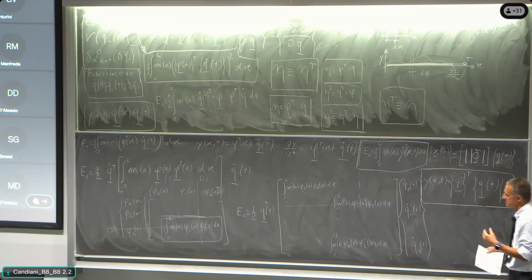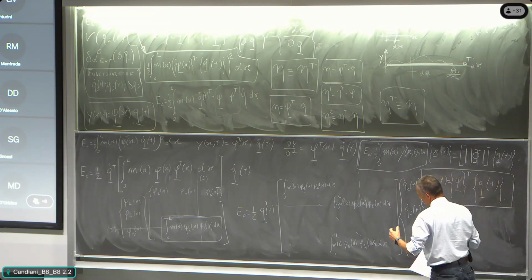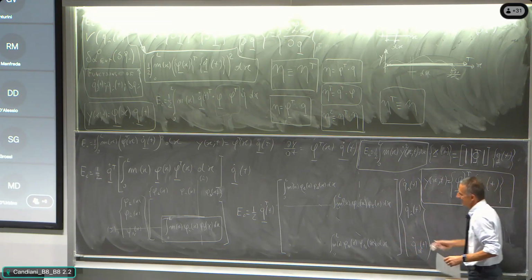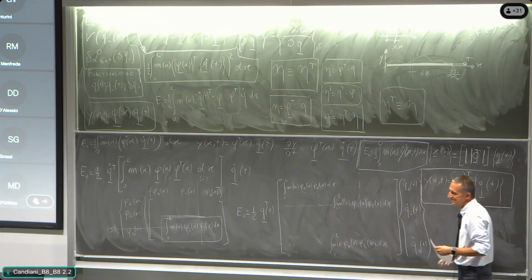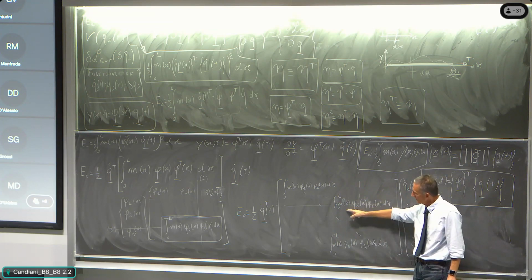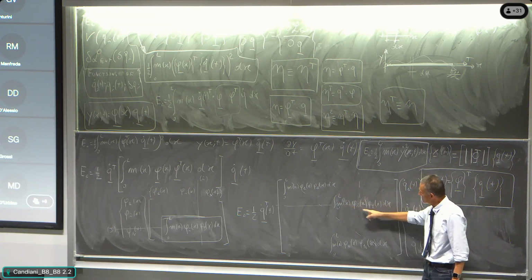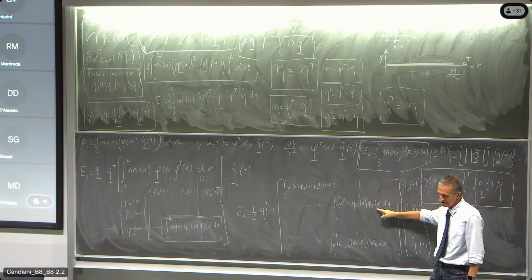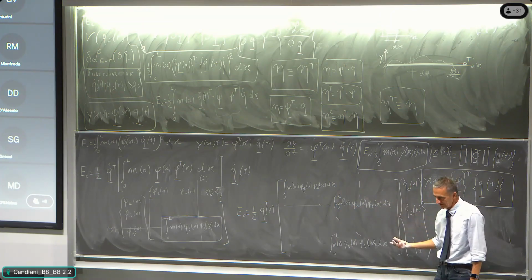In the practical approach, we are stopping because the mistake with respect to the exact solution is totally negligible. And this square matrix is telling the story of the weighting of the mass distribution through the shape of the ith mode together with the shape of the jth mode. And we recognize the orthogonality property: we can demonstrate that the i,j elements are always null in case i is different than j.